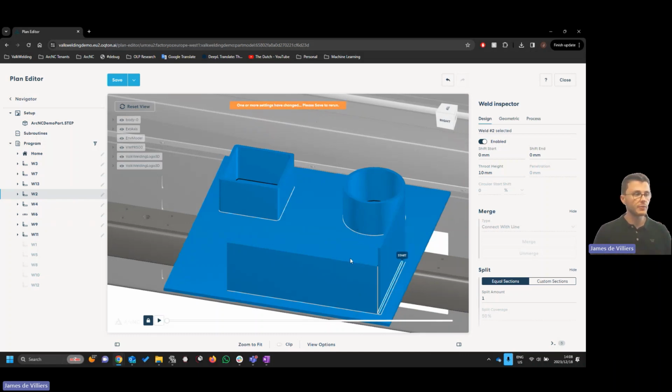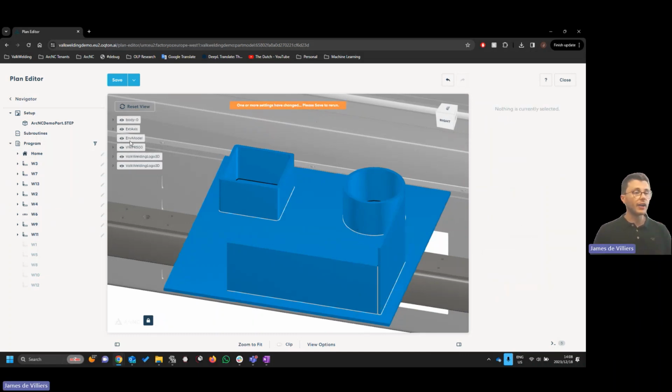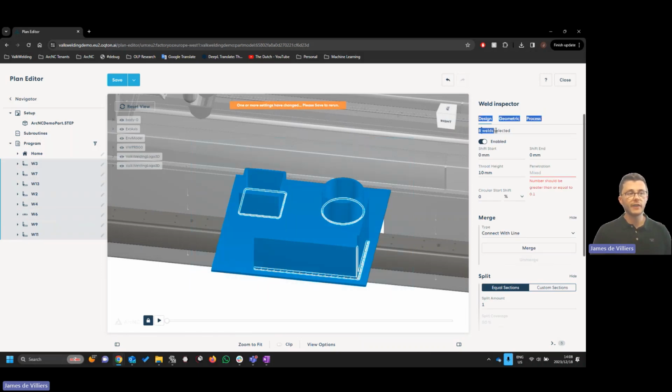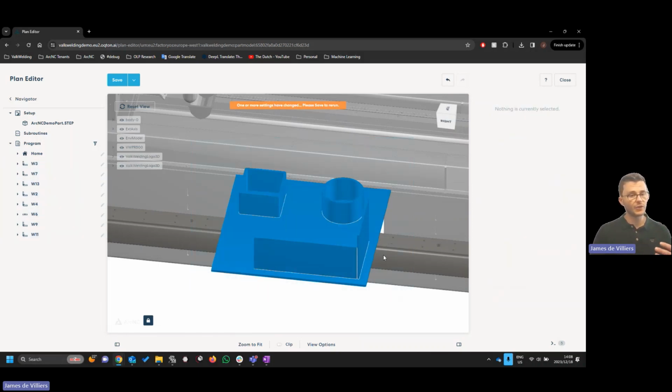This will take you more time to do. Now, like I said earlier, if I click on the view options and I don't show the disabled welds, they are now gone. So when I swipe over the part over here, you see I only have 8 welds left. This will become very useful. In more complicated parts, we will find a lot more than 13 welds, so then you can throw away a lot of them that you're not using.